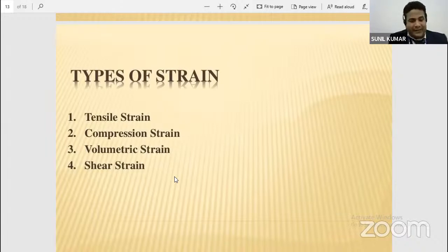So tan phi is equal to DD dash, or CC dash, on any face which is not fixed, divided by the original length H, the distance to the fixed face. Since phi is very small, tan phi is equal to phi. These are the definitions related to this type of strain.